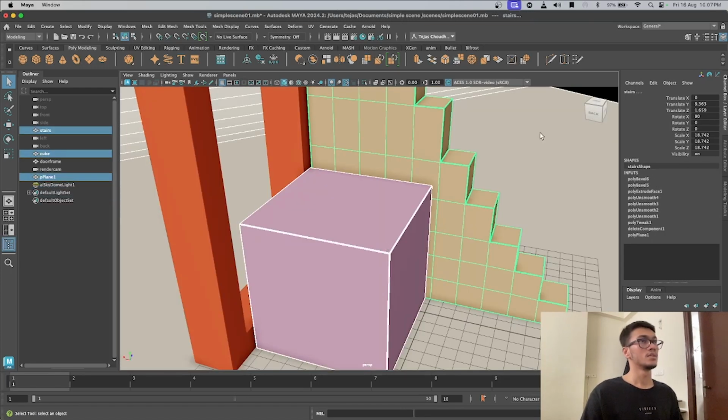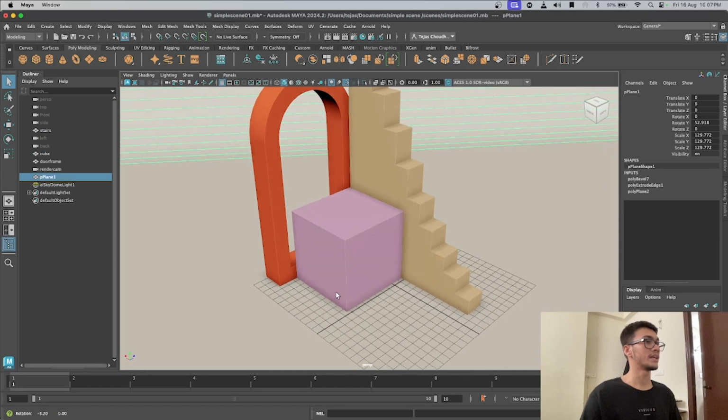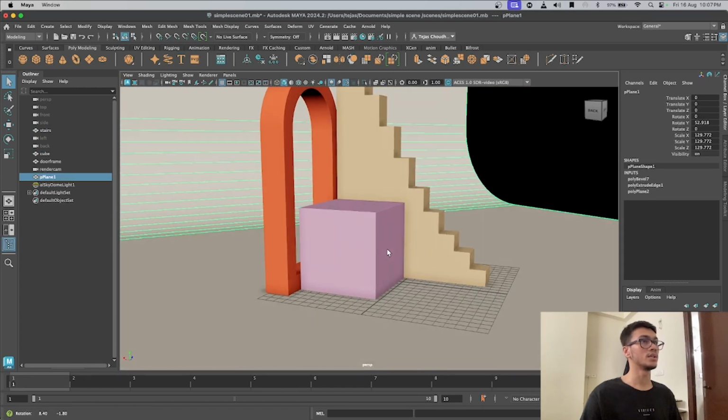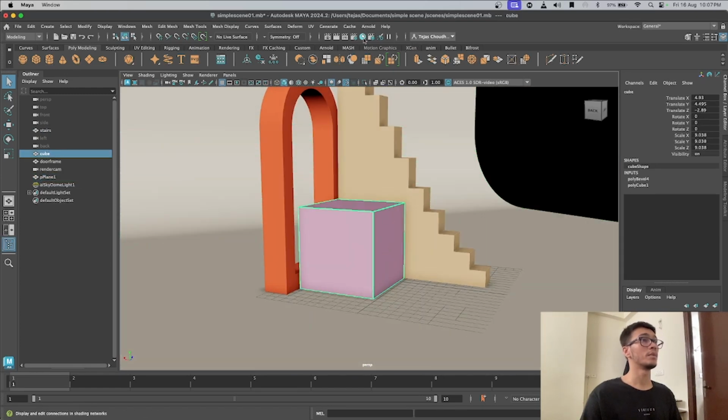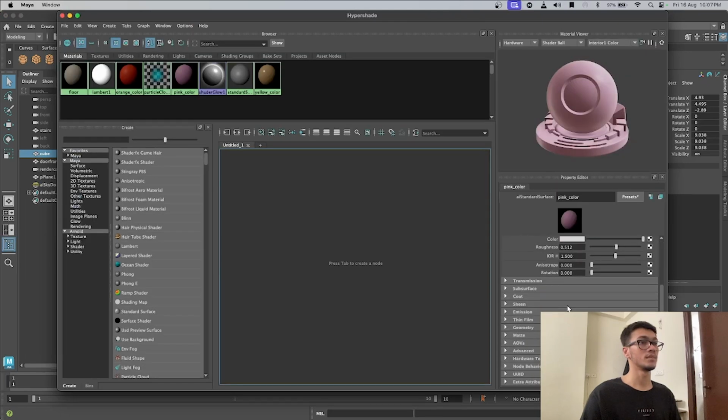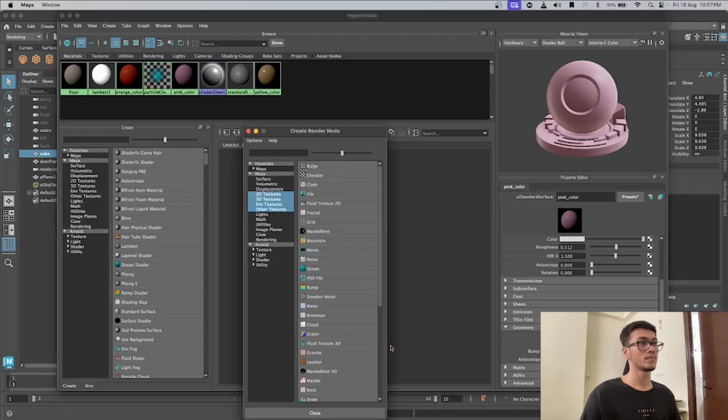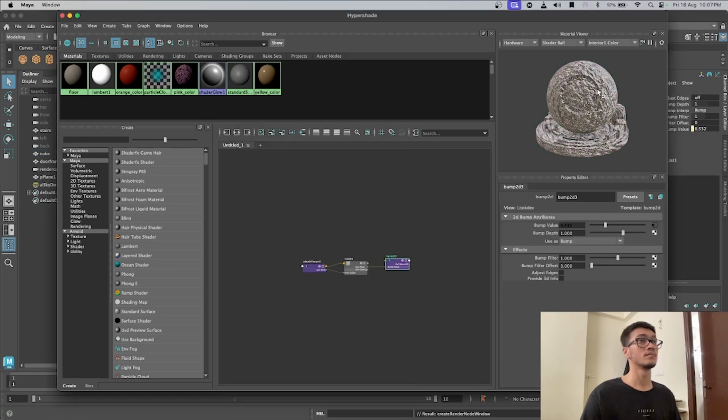Okay, so to give this a fractal texture, what I can do is go to hypershade of this material. There is a geometry tab. Click this checkbox icon, and here we have fractal. You can see it's created little bumps in that.